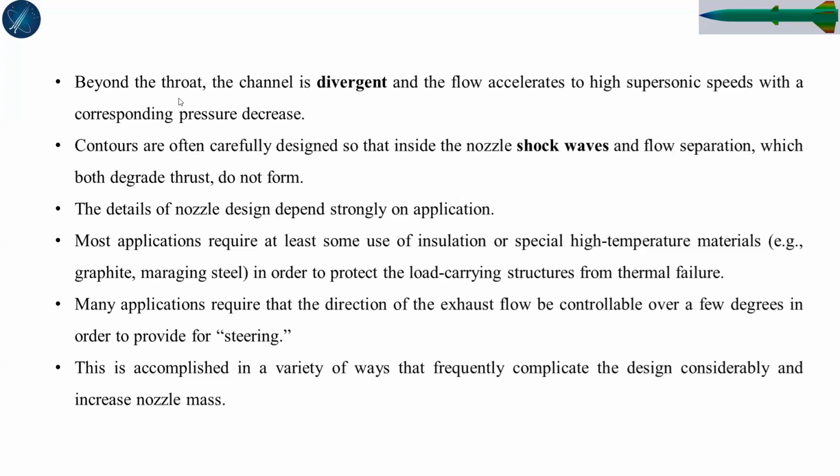Nozzles are often carefully designed so that inside the nozzle, shock waves and flow separations, which both degrade the thrust, do not form. So we have to consider this aspect also. The nozzle shock wave and the flow separation at the backside should be considered while we are designing the nozzle. These things can degrade the amount of thrust that we can obtain. And the detail of nozzle design depends strongly on application. So whatever we are designing, we have to consider which application we are using it for.